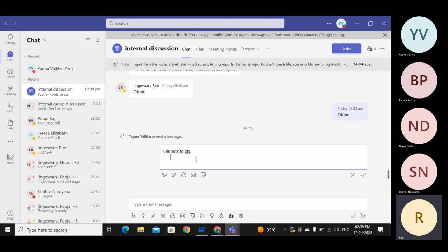Next is, in terms of the clock exception file, you are providing your float pin wherein you want a clock balance point, then you can define them and put a float there and put whatever the clock balance requirement is. If you want to stop clock construction beyond that point, add a stop pin. And exclude if that clock tree balance is not required and it's overbalancing them, because they're not really important from a skew point, then you can use an exclude pin. So use the exceptions properly and add proper DRVs, clock DRV, and which clock constructions need to happen.